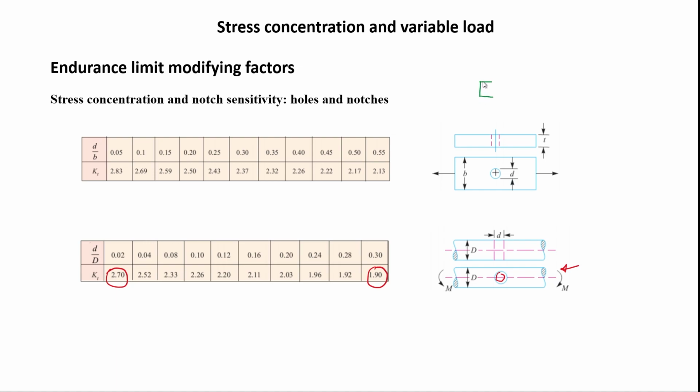You have a part to position the bearings, and then a larger part where you're going to position, for example, maybe a gear. Then you have a shoulder here, and then it's reduced to this part here. These points break the flow of the stresses created inside, and this is going to induce increased stresses that you need to account for.